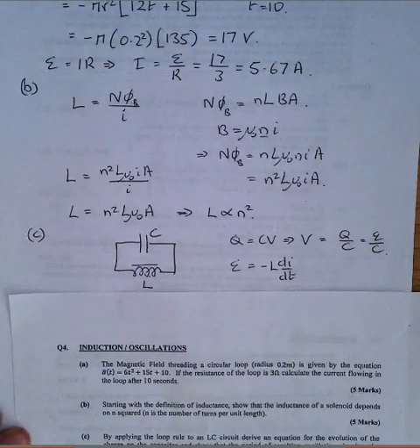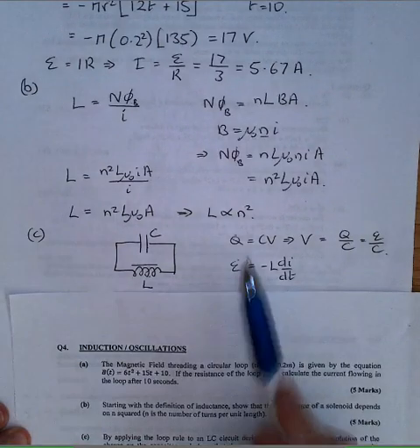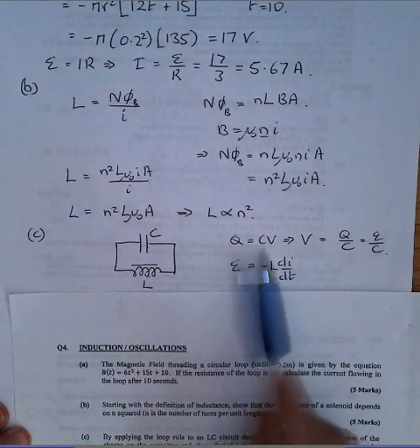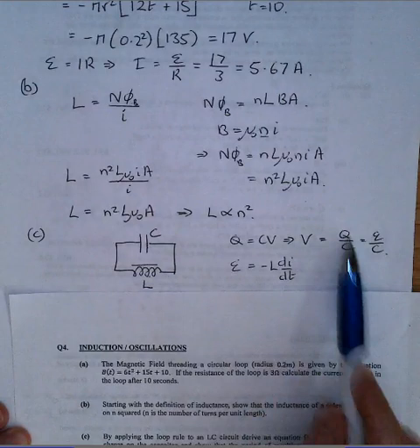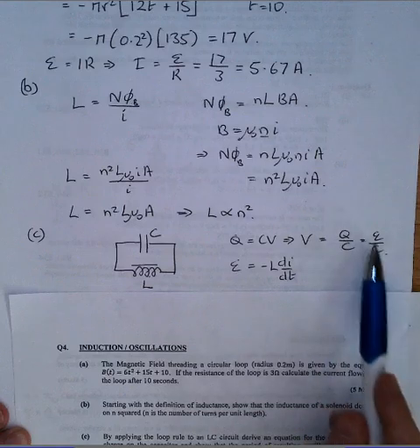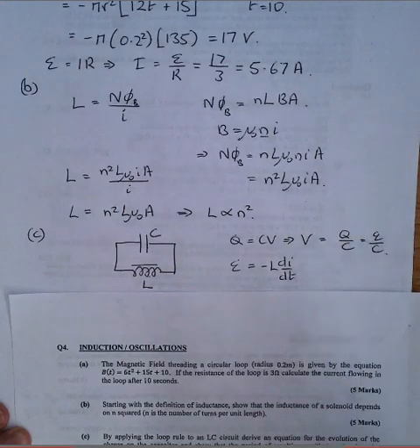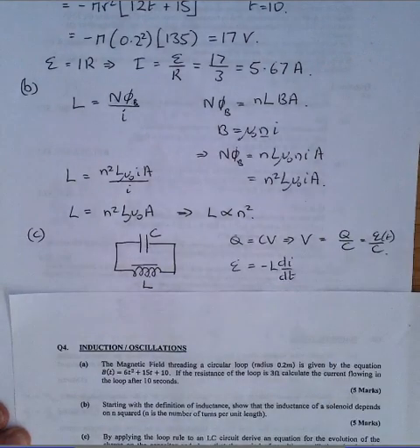So we have our series connection between a capacitor and an inductor. Ohm's law, the basic law for a capacitor, is Q equals CV, so V equals Q over C. Normally you use capital Q for fixed stored charge, but here we've got something that's going to change with time, so you can think of Q as a function of time divided by the capacitance.